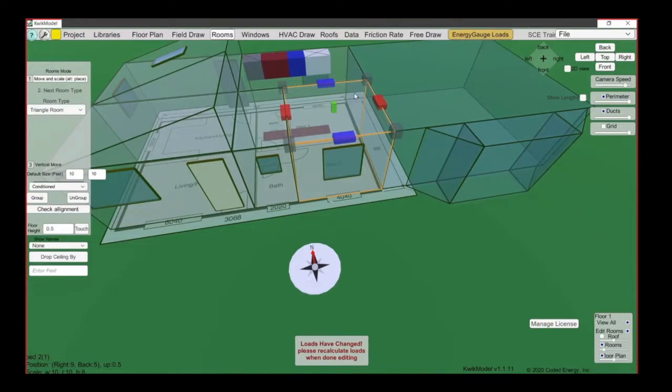And so we don't worry about these interior walls or these interior doors, but we do need to know that this ceiling is associated with this room, this wall, and this window, and then this floor. And so it's going to calculate the BTUs coming in the summertime and the BTUs leaving in the wintertime for just that room. And then we're going to do that for each and every room. We're going to add those all together.